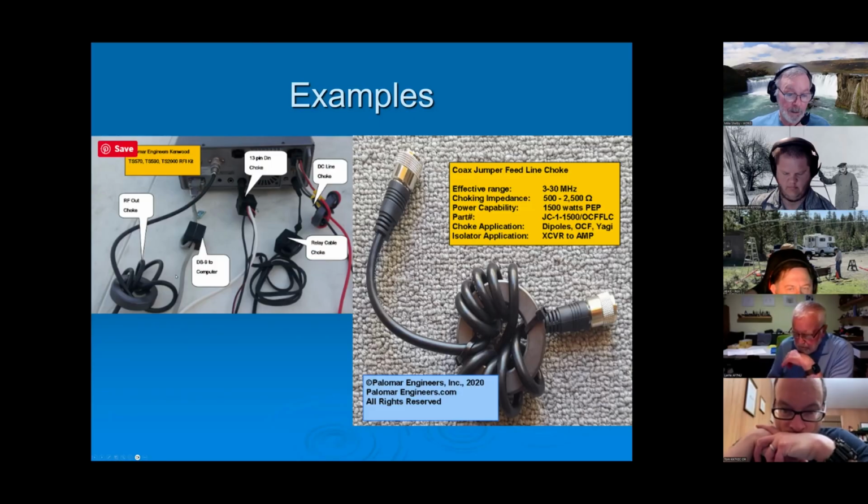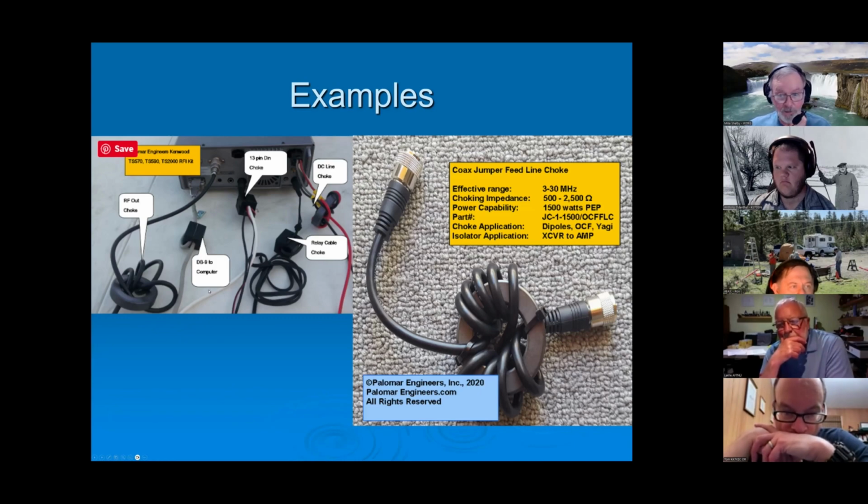You can buy a kit that has a whole package of ferrites, and you can use it for wrapping around all your cables going in and out of your rig. Every one that's going in and out of your rig, to try and stop it. So that's one way of just knocking it down, and hopefully you guessed right and got enough ferrite on any particular conductors to make the problems go away.